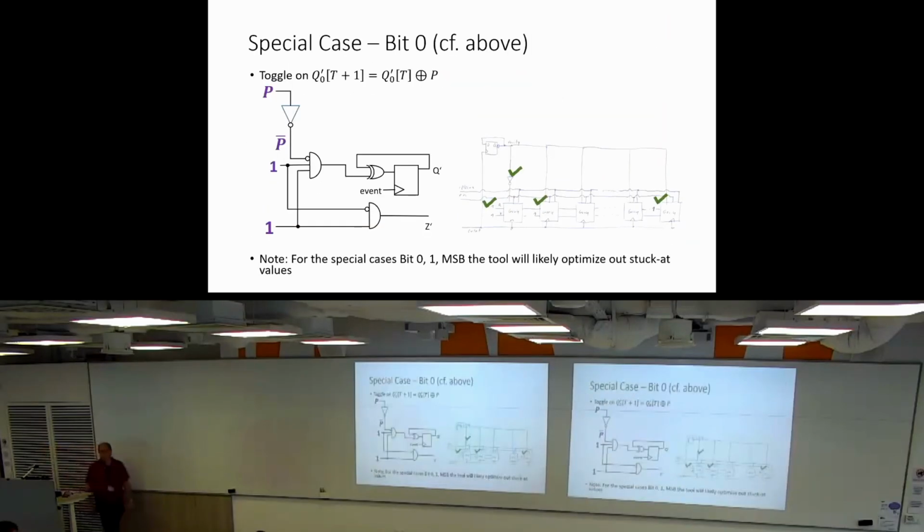The main point to see here is if you compute the output value of this after one event toggle, it goes here, the critical path from Q all the way till the last stage of such a gray counter. So for every stage, we have at least one additional gate that forwards the input here.